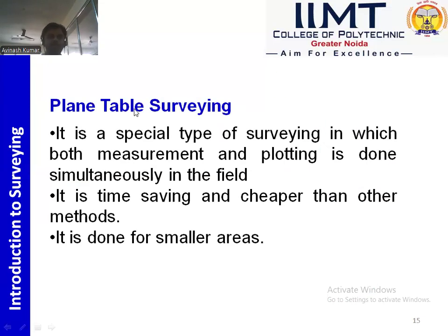Now plane table surveying. Till now we have learned about chain survey, leveling survey, compass survey, and theodolite survey. In all those surveys, we measure the land in the field and record the readings in a notebook. After coming to our office, we decode those readings and make the plan or map. But plane table surveying is different. In plane table surveying, both plotting and measurement are done simultaneously in the field.